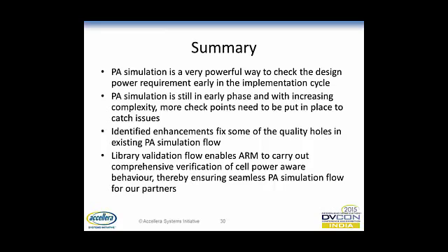So I think one, as I said, is that feed-through and floating ports are not getting checked, and because of that, simulation corruptions are happening. That is one checkpoint I discussed. Another thing I discussed is where protocol violations are happening.